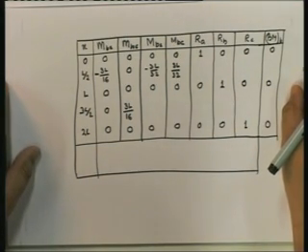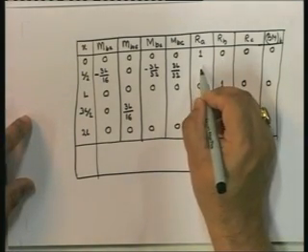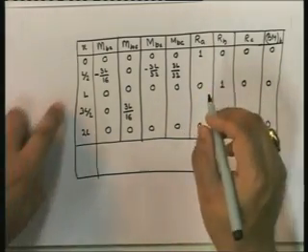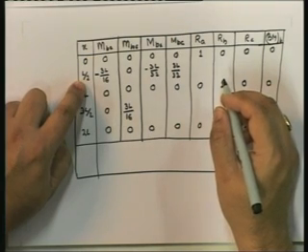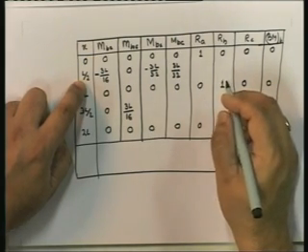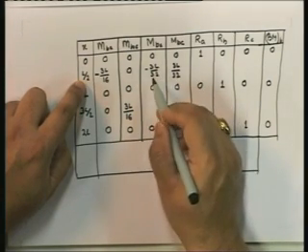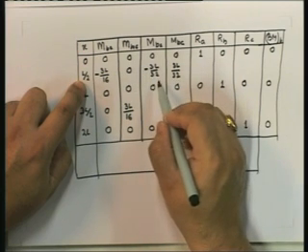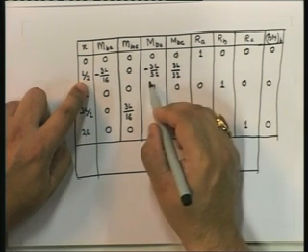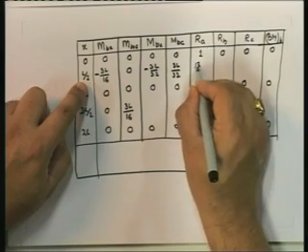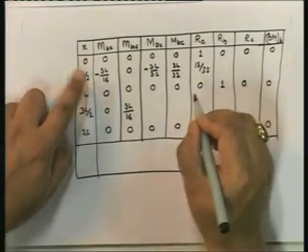Where are we? This RA is going to be 1 minus x by L. 1 minus x by L is 0.5. 0.5 plus MBA by L. MBA is minus, and so this is going to be equal to 0.5 minus 3 by 32, so that's going to be 16, so this is going to be 13 by 32 positive.